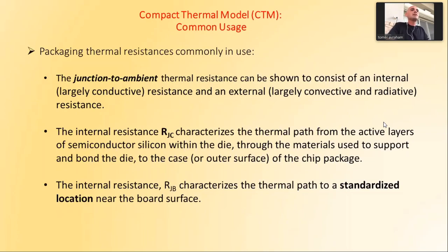You could, but you're more conservative when you solve problems with pure conduction. If you pass with pure conduction, then certainly you would pass with natural convection. So that's the thermal resistance from the junction to the top.